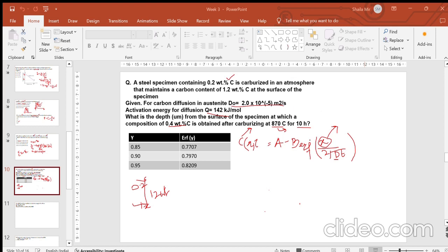This is your composition of alloy, which is having a 50% composition, and then the solidus and liquidus compositions are given. So you have to find the phase fractions. So how do you find the phase fractions for this? You have two phases. One is the liquid, one is the alpha phase, say for example. Or even if you have two phases, alpha plus beta, the same thing applies. So if you have first phase, say for example alpha, how will you find it? We have to find the value based on our Lever rule. So the value of this tie line.